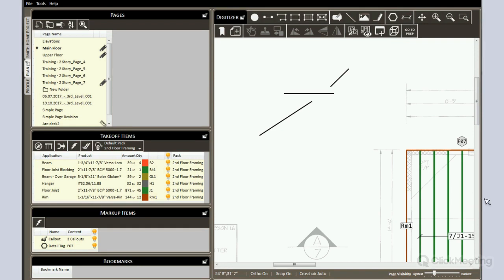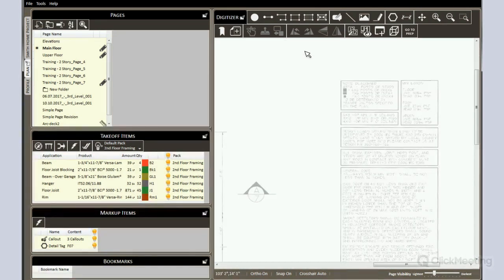Looking further down, another thing that we've introduced relates to drawing containers or drawing areas. We've introduced a new way to draw them, and that is basically a rectangular draw of a container. So I'm going to use a floor container to demonstrate this. If you left click on the tool, then you get the standard behavior as you always have.